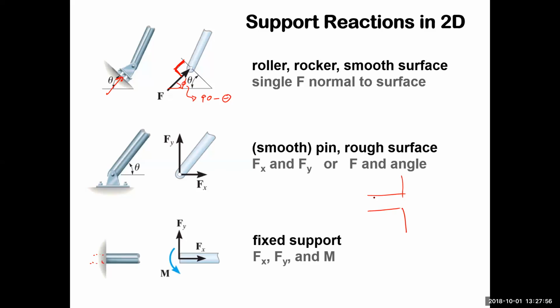If you stuck a plank or something in a slot, that plank would start to droop, and it would rest on the rim here, which would be providing a force pushing back. And also internally, it would rest on the ceiling of that slot. And these two forces would provide the couple moment, separated by some distance. So this M would be the F times D of these two forces acting to hold that thing up, right? That's how you get that moment in there.